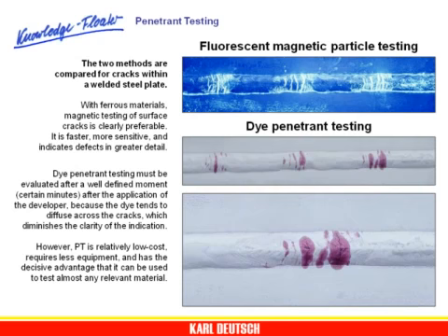Dye penetrant testing must be evaluated after a well-defined moment, certain minutes, after the application of the developer, because the dye tends to diffuse across the cracks, which diminishes the clarity of the indication. However, penetrant testing is relatively low cost, requires less equipment, and has the decisive advantage that it could be used to test almost every relevant material.